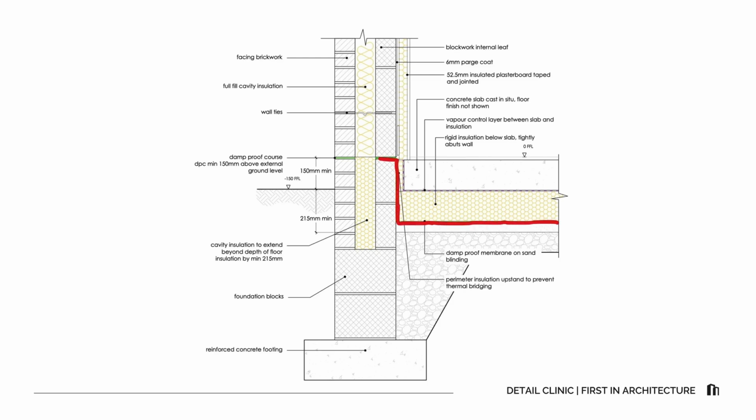Continuity is really important. Moisture barriers like DPMs and DPCs and thermal layers must read as continuous lines. Keep the DPC clear of finished ground level, which is usually 150 mm. Maintain the required clearance so rain splashback and bridging don't defeat the DPC. Mind the cavity. Keep it clear of mortar droppings. The ties should not become pathways for moisture inwards.